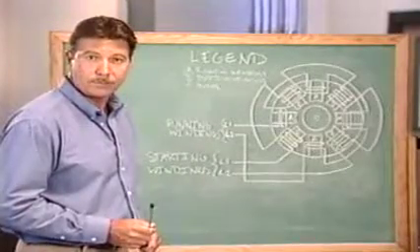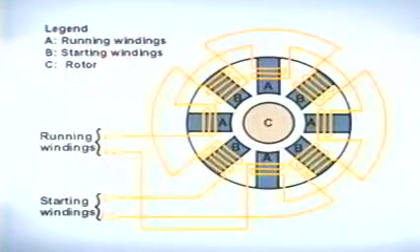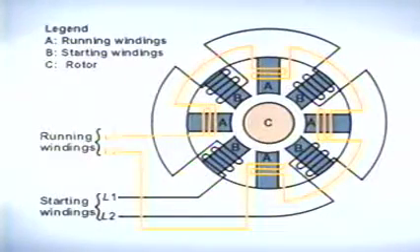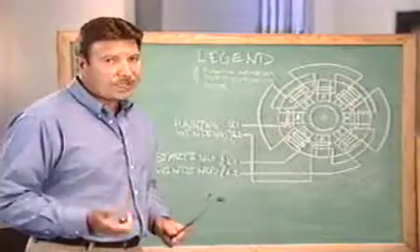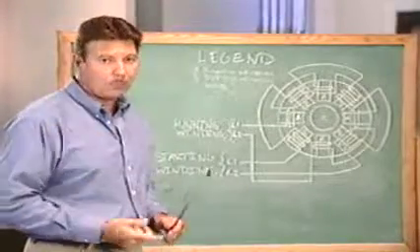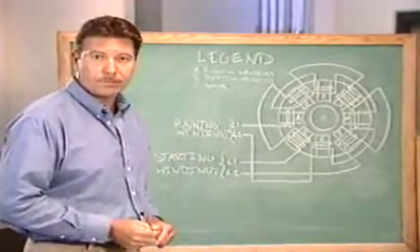for the motor. Once the motor reaches a speed within 75% of its running speed, the centrifugal switch opens, de-energizing the start winding. The motor will continue to operate with only the run winding energized. Once the motor is de-energized, the contacts on the centrifugal switch will close in preparation for the next start.